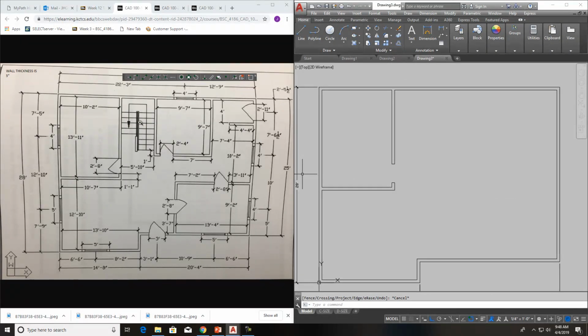And here on these stairs, all I want you to do is, usually stairs are about 10-inch treads. So just count these up and then just eyeball it in there. And we'll go ahead and we'll put some of that in. 5'10". So offset 5 foot 10 inches. And I'll show you how to put the stairs in real quick.